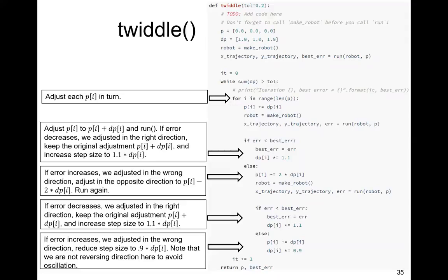just the three PID parameters in turn. The P is in here. It has three control parameters, initialized all to 0. So length P is 3. You have PID 3 parameters, and then you update the P with dP, kind of like a gradient descent operation. Increment P[i] with amount dP[i], and you run the robot for two n time steps in this program.